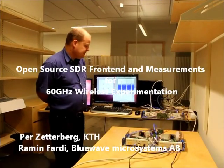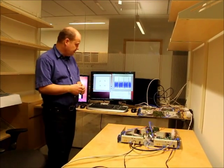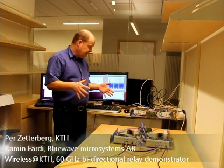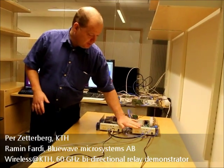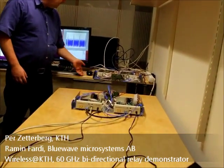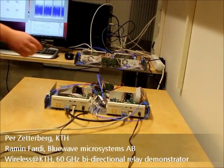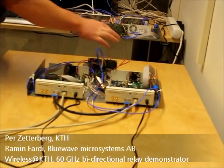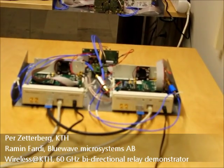Welcome to this wireless at KTH project demonstration of 60 GHz MIMO setup. In this case we are using commodity software defined radios, USRPs, to generate baseband signals at the transmitter and the receiver. And we're using the so-called basic daughter boards for the USRPs, and then we're connecting them to some boards developed in the project.